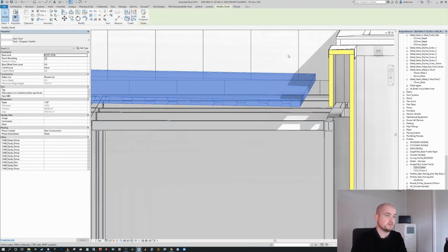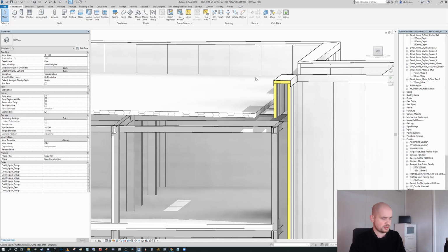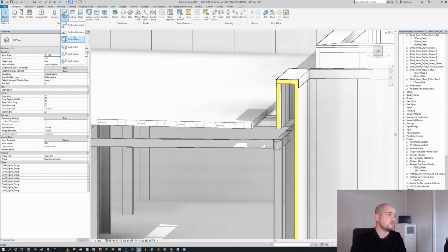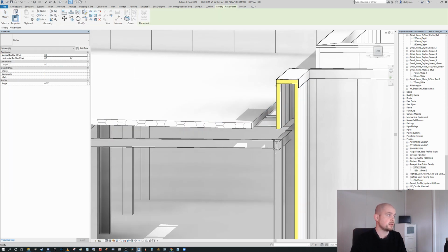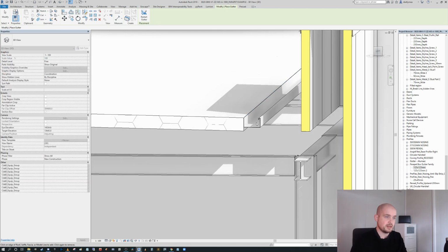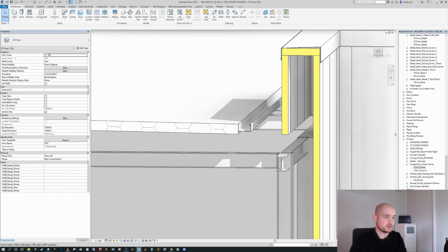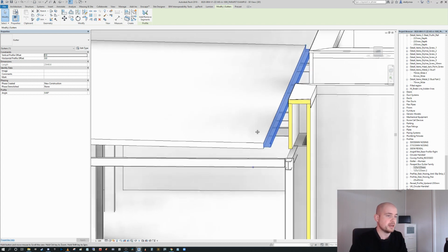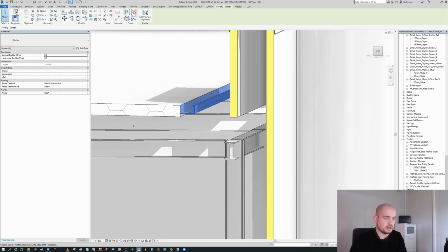So what we're going to do here to start is I'm going to show you an example of a gutter being placed on this, and then I'm going to develop a new one that we can replace it with. So if I go to roof and go to gutter, I can select gutter from the selection criteria there, and you typically pick the top edge, the leading edge, when you're selecting the roof. When I select that, needless to say, that's not a suitable gutter type. This is a typical edge box gutter type rather than a hidden parapet gutter. So what we have out of the box in Revit is not going to suit this use case.